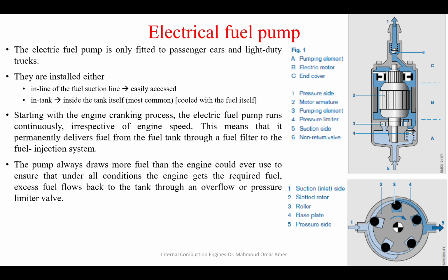The pump always draws more fuel than the maximum needed from the injection system. Why? In order to make sure that at any driving condition we have the sufficient amount of fuel that the system needs. Okay? So what happens to the excess fuel that is drawn? It returns back to the tank. And this excess fuel also helps in cooling the high pressure pump and the fuel system.